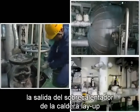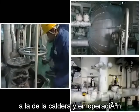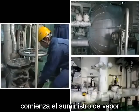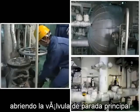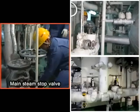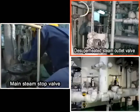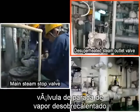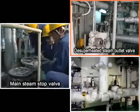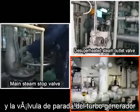Once steam pressure of the layup boiler's superheater outlet has become almost equal to that of the boiler in operation, begin supplying steam by opening the main stop valve, desuperheated steam stop valve and main turbo generator stop valve.